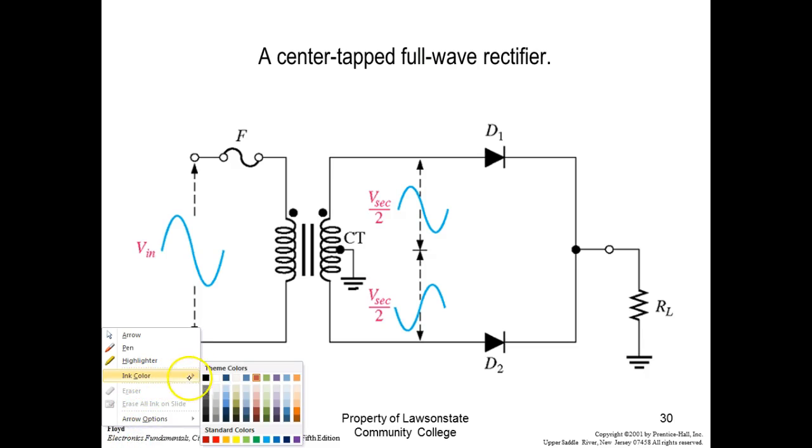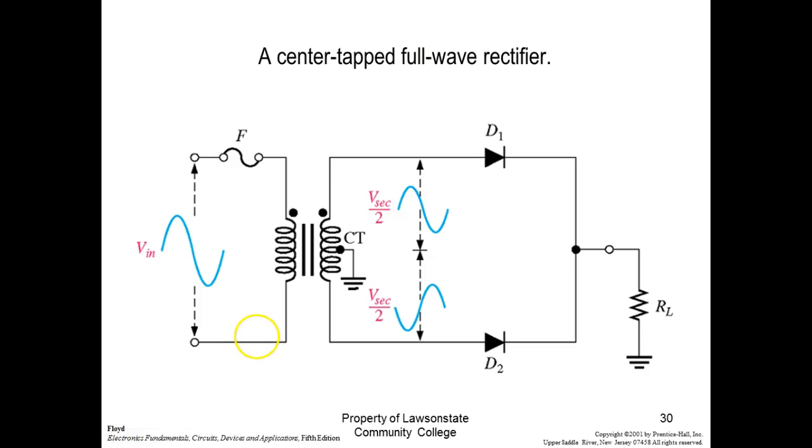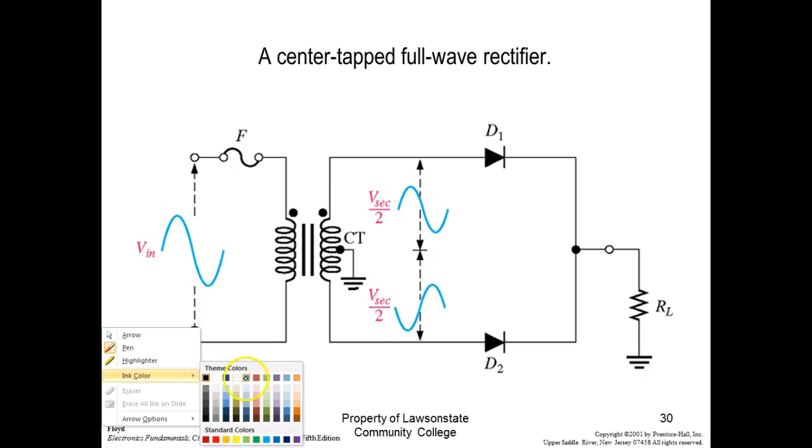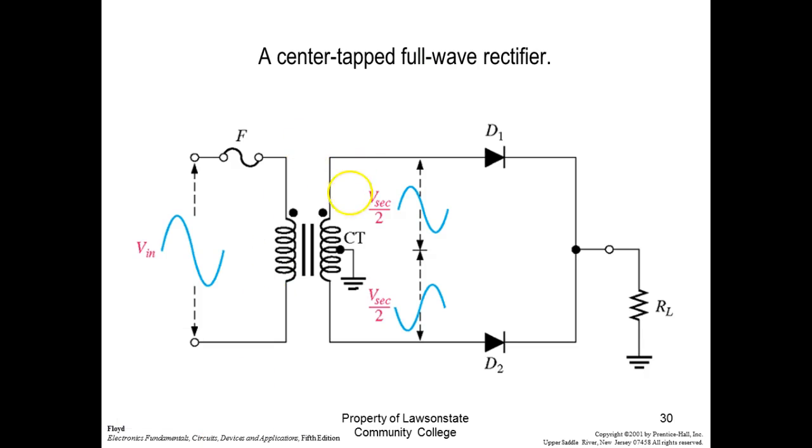And then we'll understand our calculations are going to be a little different. So if this is 12.6 volts, then between here and the center tap we'll get what? 6.3. And then here we'll get 6.3.